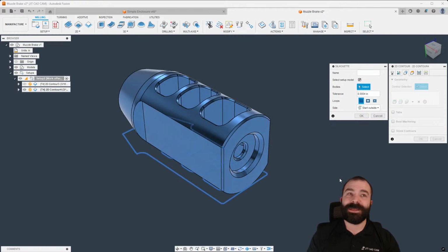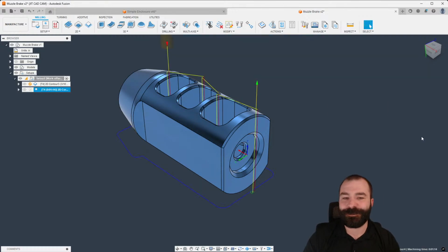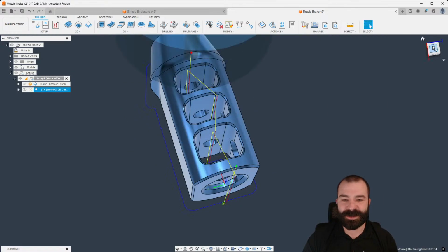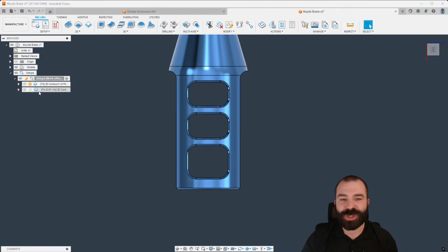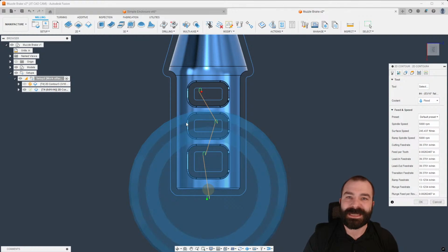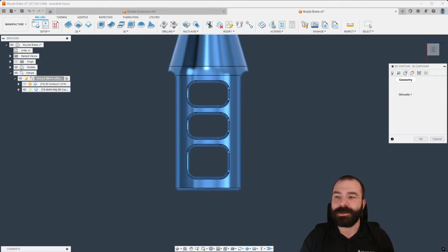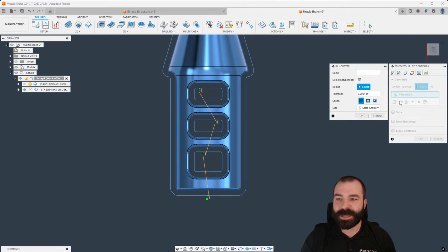And what I like to do, and this is a big thing to me, guys, I can't stress this enough. A lot of people go in when you're new and you click way too many buttons. We'll say a lot of you that are also experts go in and click way too many buttons, right? Let's see what we get for blue lines, and then let's make our adjustments from there. As you can see, we're doing the inside profiles here. Maybe I don't want to do that with this tool. This radius here might be smaller than the radius of this tool, so we can adjust it. The best thing about Fusion is the speed at which you can get blue lines on your part and troubleshoot it, right? So we can go back to our silhouette.